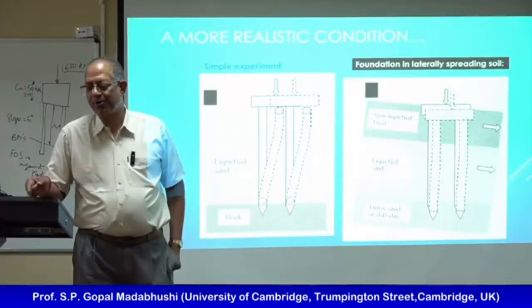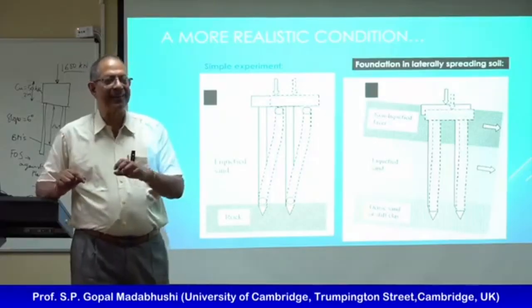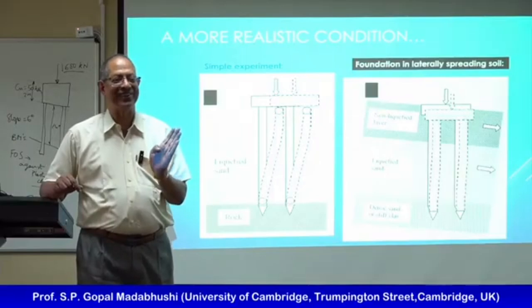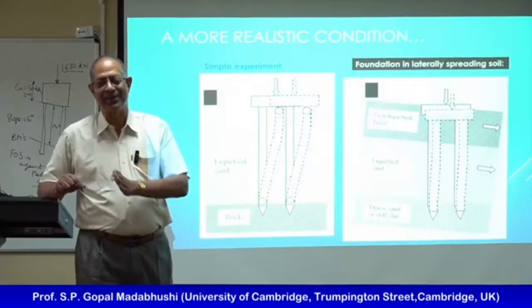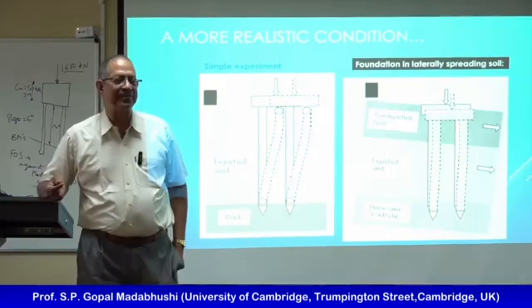During liquefaction, one of our current projects is we got a monopile, we liquefy the soil and pull the monopile through the liquefied soil before the pore pressures are dissipated. The results are yet to come, but that's something we are trying.